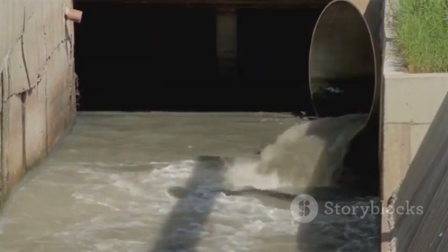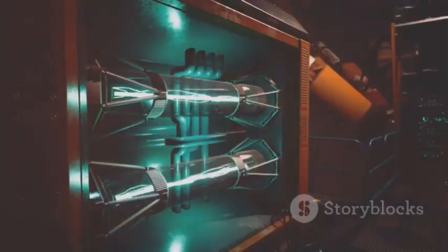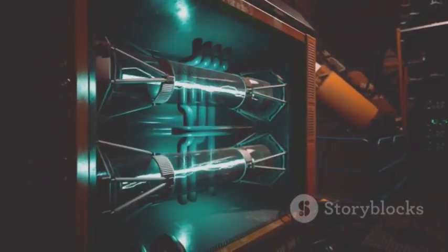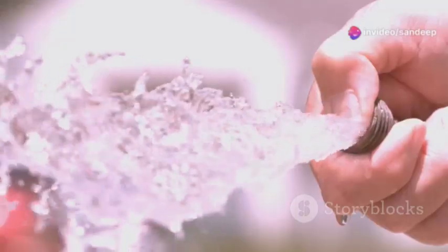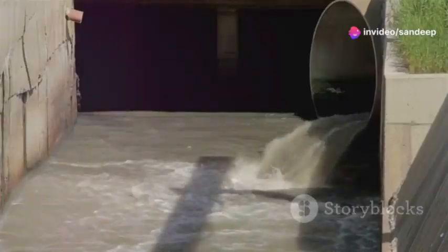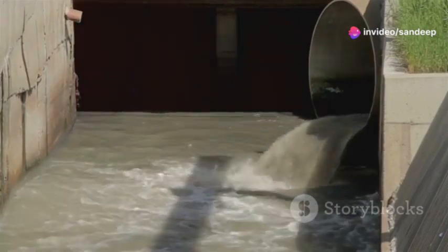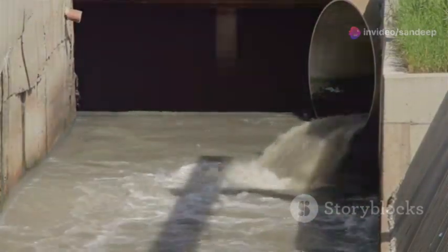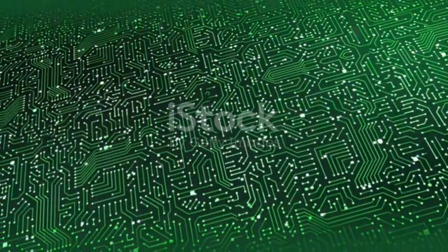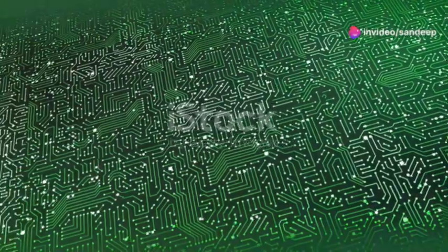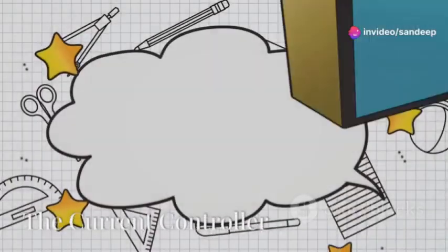Increase voltage, and current increases if resistance stays the same. More pressure in a hose, voltage, means more water flow, current. Increase resistance and current decreases, keeping voltage constant. Pinching the hose adds resistance. The flow of water, current, decreases even though the pressure, voltage, stays the same. Mathematically, Ohm's law is V equals I times R. This simple equation helps us understand and calculate electrical quantities in circuits.